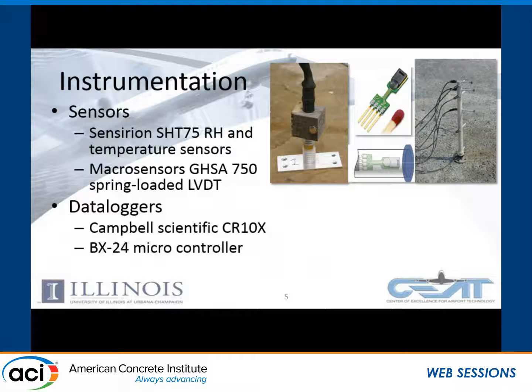And so the first thing we developed is what we call our slab liftoff sensor, but all it is is an LVDT that we've turned up on end, that we affix the core to a steel plate here on the bottom, and then the rest of the LVDT is positioned vertically. That steel plate is affixed to the base because a lot of the base under the concrete will be things like asphalt or cement treated permeable base, lots of different variations. And so we affix the base of the LVDT under the slab, and then that way, as soon as the slab starts to lift off in the corners, we can actually measure that. This is kind of counterintuitive. You don't think of a slab actually lifting itself off, but we have measurements to show you otherwise.